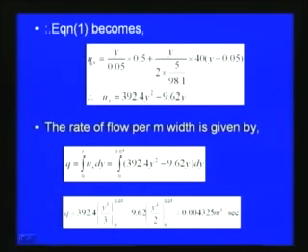So, the velocity ux is equal to y by 0.05 into 0.5 plus y by 2 into mu, which is 5 by 98.1 into 40 into y minus 0.05. From this we get an expression for the velocity as ux is equal to 392.4 y square minus 9.62 y. So finally we got an expression for the velocity, by substituting the various values.